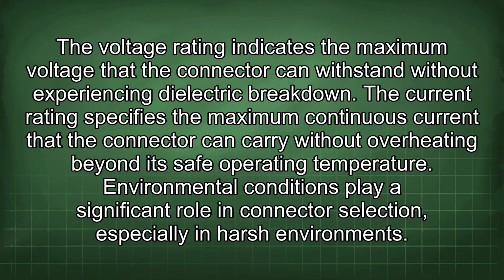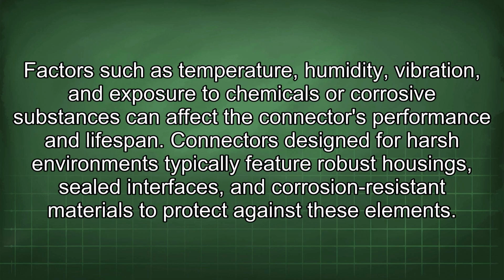Environmental conditions play a significant role in connector selection, especially in harsh environments. Factors such as temperature, humidity, vibration, and exposure to chemicals or corrosive substances can affect the connector's performance and lifespan. Connectors designed for harsh environments typically feature robust housings, sealed interfaces, and corrosion-resistant materials to protect against these elements.